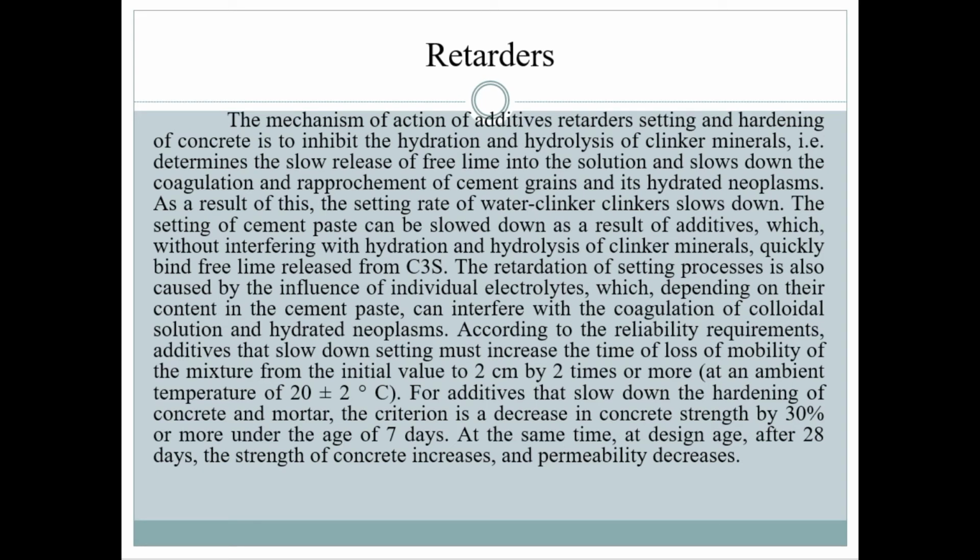The setting of cement paste can be slowed down by additives without interfering with hydration and hydrolysis of clinker minerals, quickly binding free lime released from C3S.